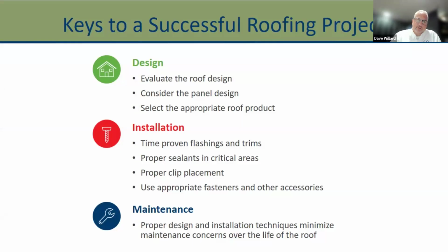Then, of course, when it comes to installation, we want to make sure we've used time-proven flashings and trims, potentially sealants in critical areas, although if things are properly flashed, sealants end up being a maintenance issue. So we like to have everything be nicely and properly flashed. We talk about proper clip placement for panel adhesion and appropriate fasteners and other accessories. So there's a lot that goes into that installation part of it.